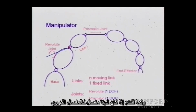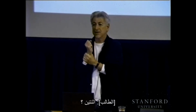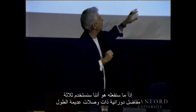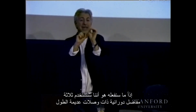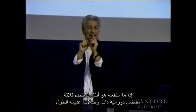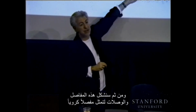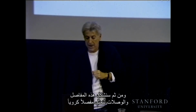And if we have a joint like a spherical joint, do you know how many degrees of freedom a spherical joint would have? 2? 3, yeah, 3. So what we would do is use 3 revolute joints with 0 link length, and then introduce these joints and links to represent a spherical joint. Okay.